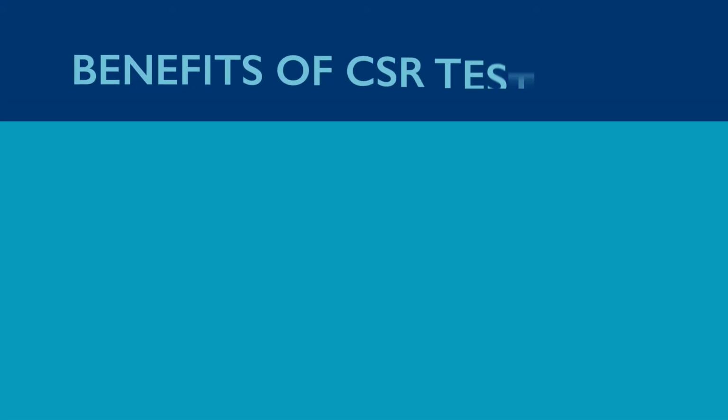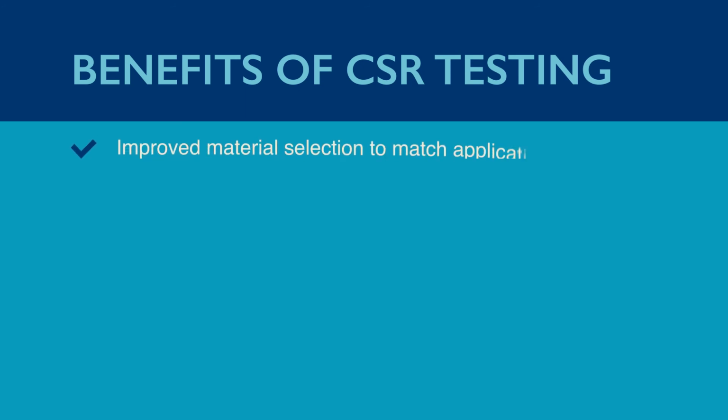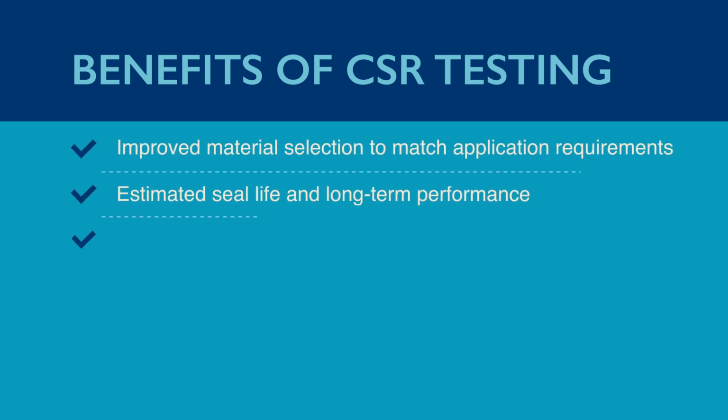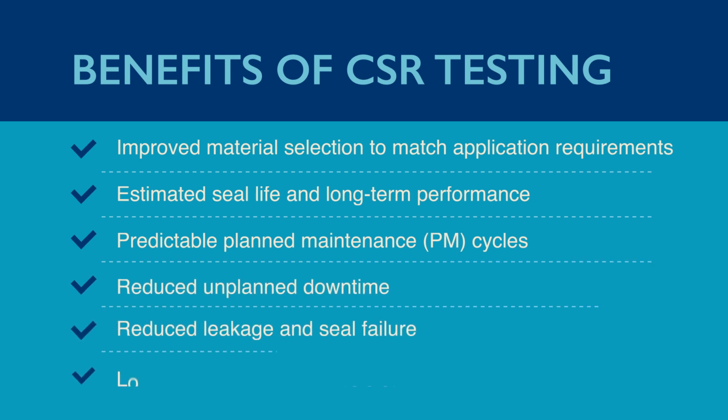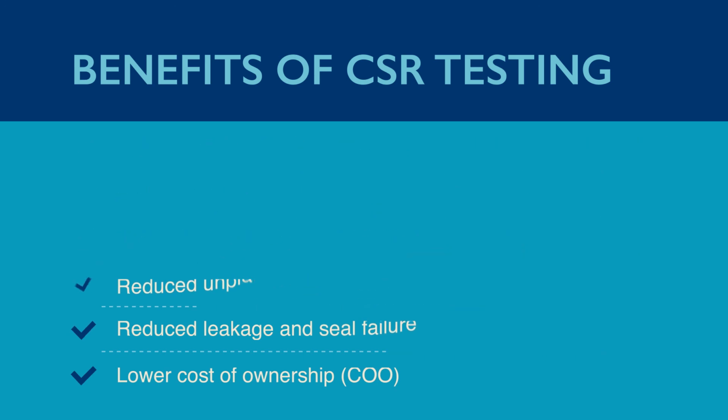Conducting CSR testing on sealing materials that match your application conditions relating to operating temperature and fluid media can provide several benefits. Most notable, the ability to benchmark materials for long-term sealing performance, with a prediction of estimated seal life, which helps with planning preventative maintenance cycles.